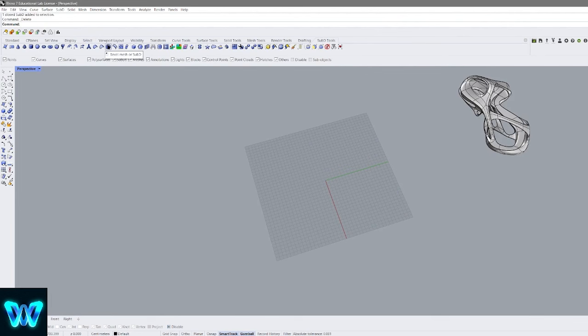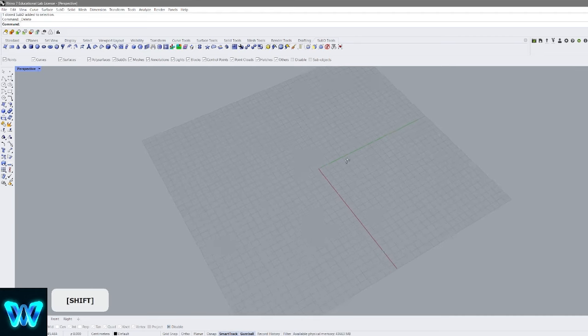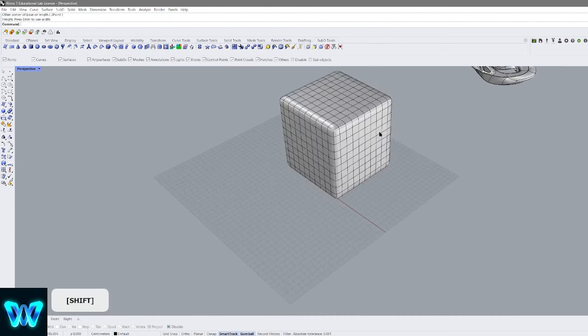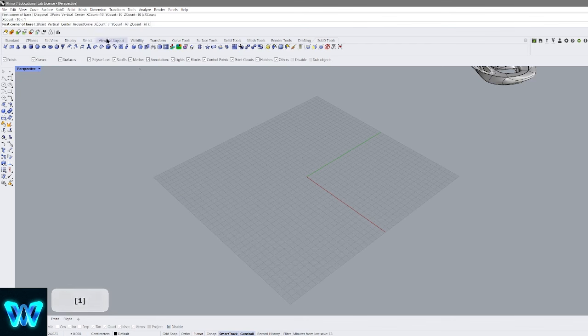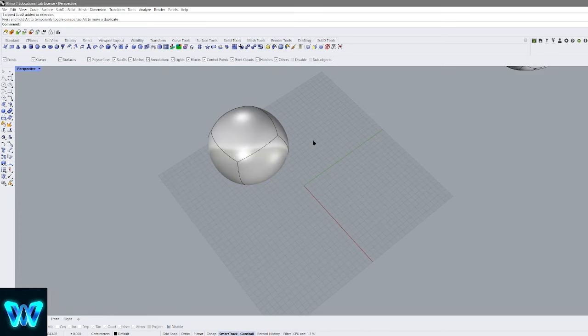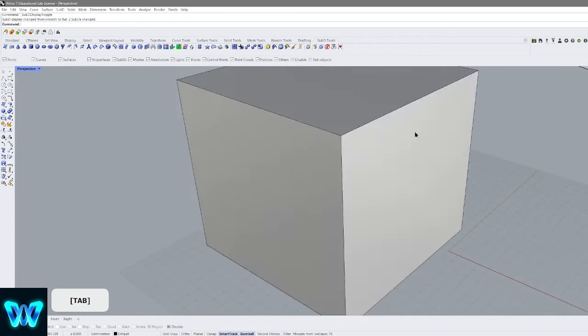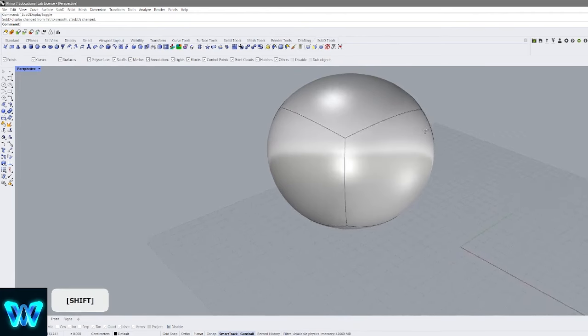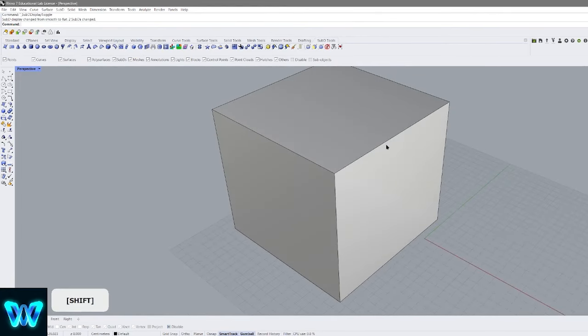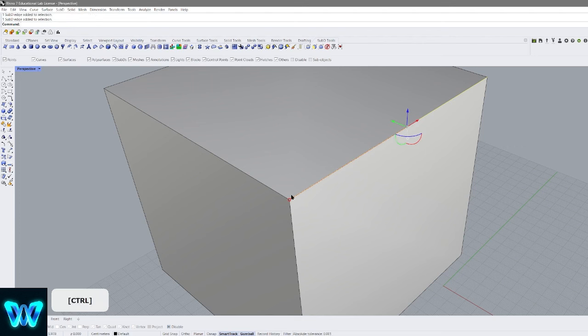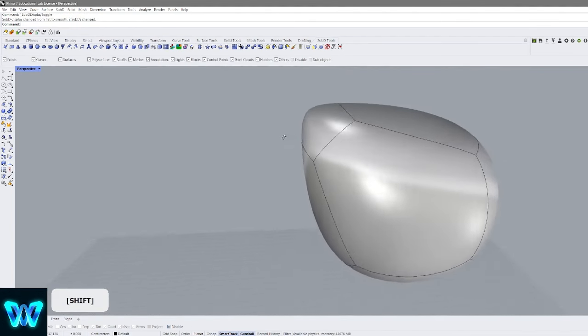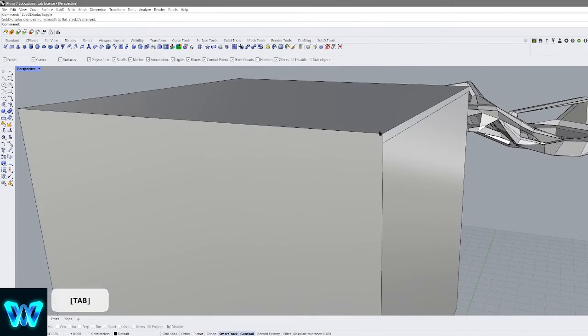really useful. Right here we have bevel mesh or SubD. All it does is create a bevel on a corner area. So for example, it works backwards from what you would expect. Actually, let me make a 1 by 1 by 1 cube. In a normal polygon, the moment you bevel, you're just trying to make a corner area curvy, right? In this case, it's backwards, because the moment you add a new edge here, now I add more detail to it, so it'll corner it more, right? Because there's less to round up. So that's what I'm doing when I'm beveling.